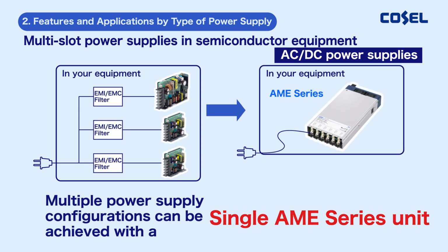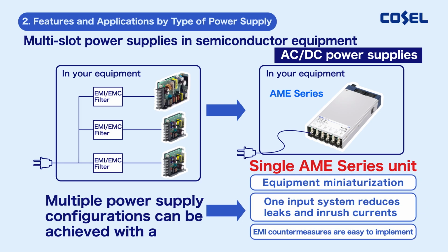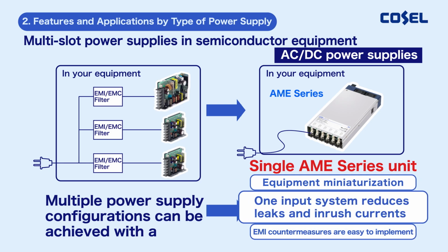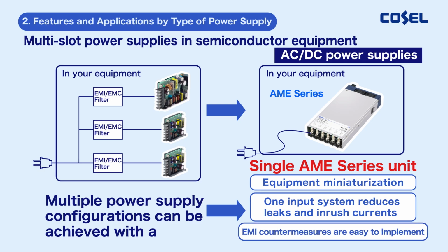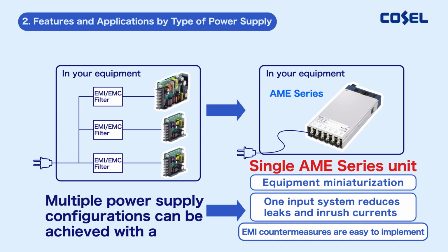Power supplies previously used in multiple configurations can now be consolidated into a single multi-slot power supply, which has a single input system, reducing leaks and inrush currents. In addition, EMI countermeasures are easier to implement because noise impacts from multiple power supplies are eliminated.